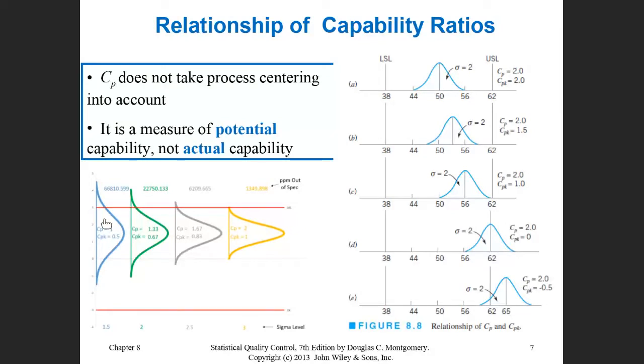And here is another example, maybe it shows you the explanation in a different way. We have a CPK high in here. For example, the CP is decreasing from 2 to 1.6 to 1.3 until 1, and the CPK is also decreasing. What we can see here, when we have a CP high, the highest is 2 for both of them, and we will talk about the threshold and each number, what it represents.